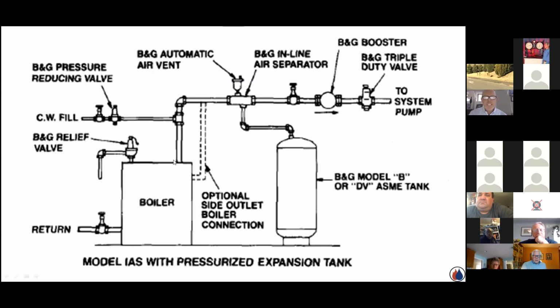And the reason for that is this: when that water gets heated and it releases some air bubbles and the circulator's on, the water and air are rising up this riser and it encounters this elbow. And this elbow causes turbulence. And when I have turbulence, some of that air rides along the bottom of the pipe.